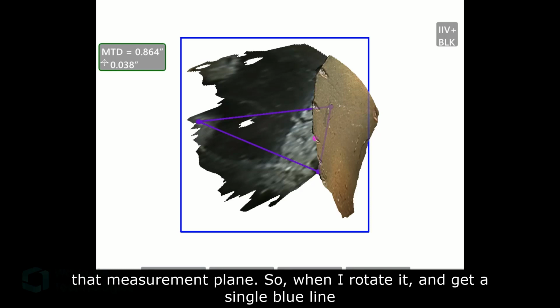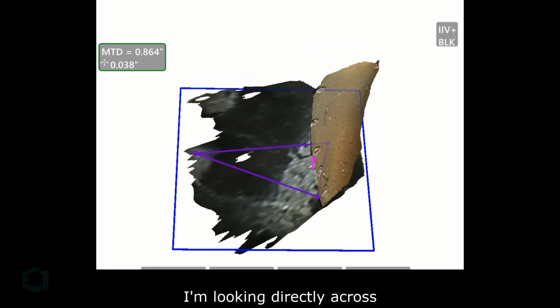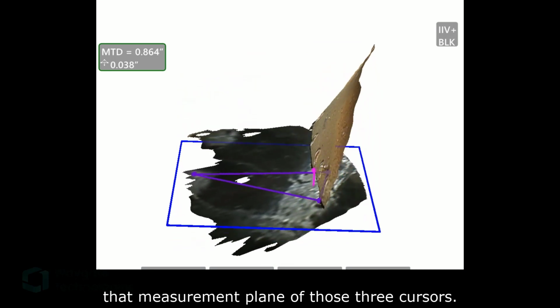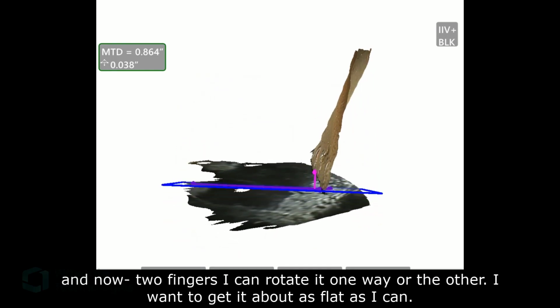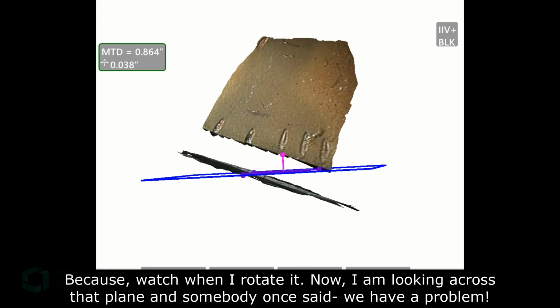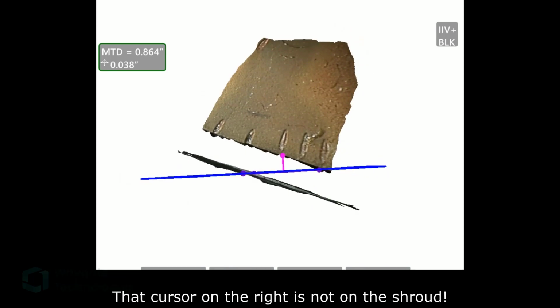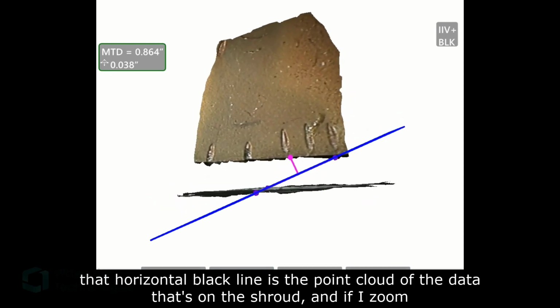So when I rotate it and get a single blue line, I'm looking directly across that measurement plane of those 3 cursors. And now, 2 fingers, I can rotate it one way or the other. I want to get it about as flat as I can, because watch when I rotate it. Now I'm looking across that plane, and somebody once said, we have a problem. That cursor on the right is not on the shroud. And as a matter of fact, if I rotate it, that horizontal black line is the point cloud of the data that's on the shroud.